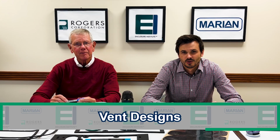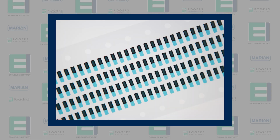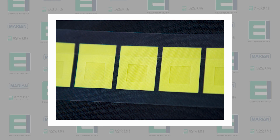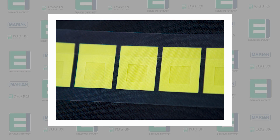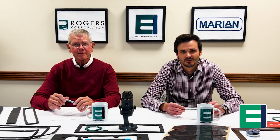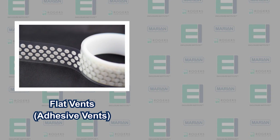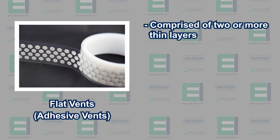Now that we've established why a vent is needed in the enclosure, let's talk about vent designs. The first thing you need in your sealed enclosure is a hole, but you will then need to plug or cover that hole with the correct material that allows air to pass while withholding moisture and dust. There are many manufacturers of molded plastic plugs that mechanically fill the hole and contain filter fabric within the plug, but for simple designs, a flat vent is usually all that's required and is much less expensive. Flat vents, also sometimes called adhesive vents, are comprised of 2 or more thin layers.